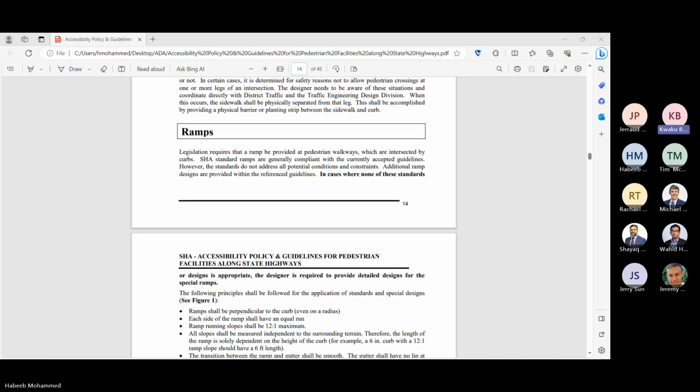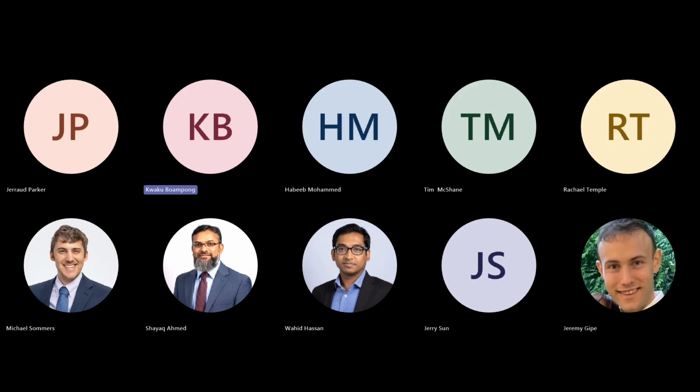I think when your roadway grade exceeds 5%, all sidewalk outside of the ramp can match that roadway grade, which allows you to tie in easier when you get to the ramp to maintain that 12-to-1 and that 2% for your landing area. Does that make sense? Yeah, that's correct. So you should still have a 12-to-1 leading up to your landing area, because you don't want a wheelchair going down too fast, potentially falling off the landing area from the ramp itself.